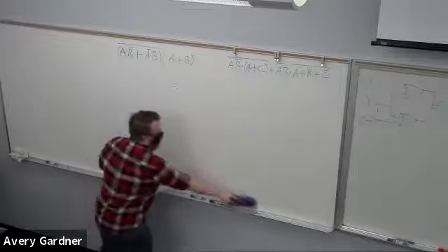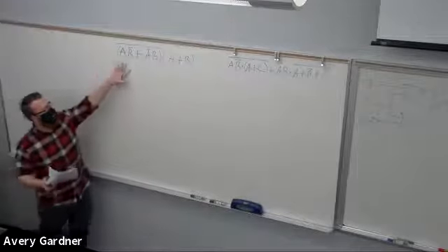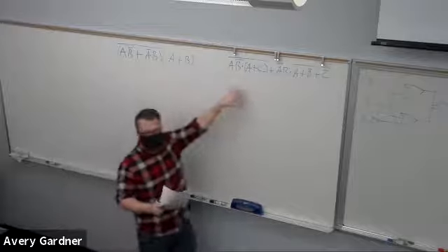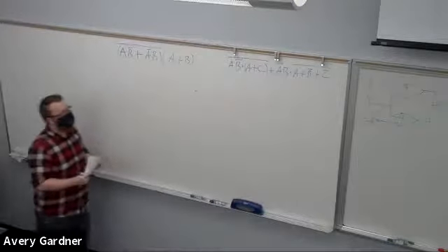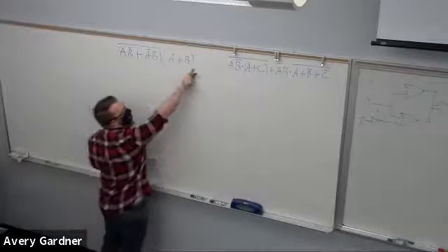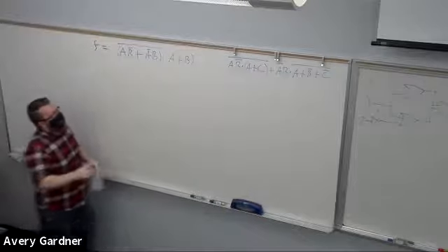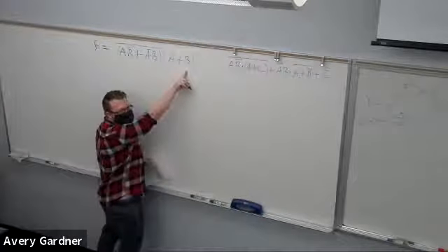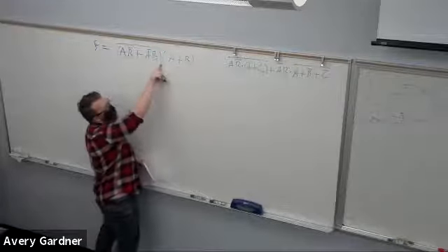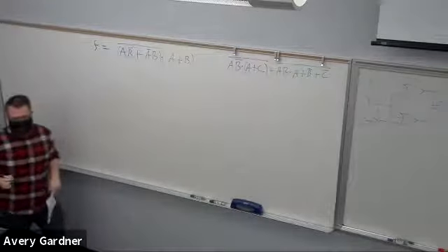Okay, so let's just start off with this example of De Morgan's and go through and simplify it, and then I'll have you guys attempt to do this one on your own. Okay, so this portion of the equation, right? So this is going to be something like f is equal to that, right? This isn't really problematic. That's an easy OR gate to draw out, right? Plus sign is OR, multiplication, whether implied or explicit, is AND gate.